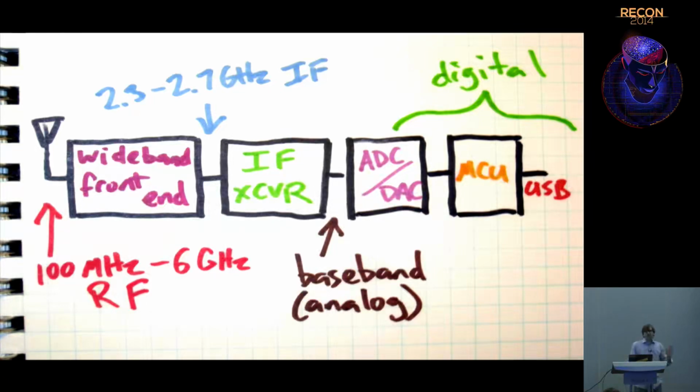So depending on the range of those two components, the operating frequency range, we can choose whatever RF we want. And because the wideband front end mixer actually has a wider operating frequency range than the intermediate transceiver does, that means we can tune all the way down to 0 hertz without any trouble. The trouble is what kind of performance do we get around 0 hertz. So there's no limitation against you tuning to 0 hertz. It's just what will you get there.